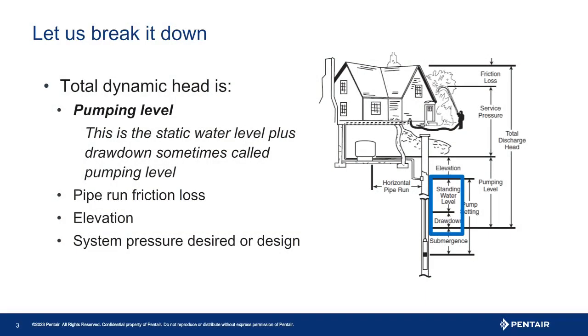A good starting point is the depth to water, both standing and to what depth the water will drop to when pumping. Sometimes this is called the pumping level or working level, to name a few. Who determines this? The well when drilled is tested by a variety of methods we do not need to cover here. It is also a good idea to retest the well when changing out the pump to ensure that the well production has not changed.